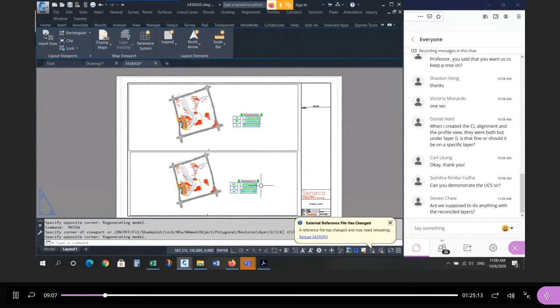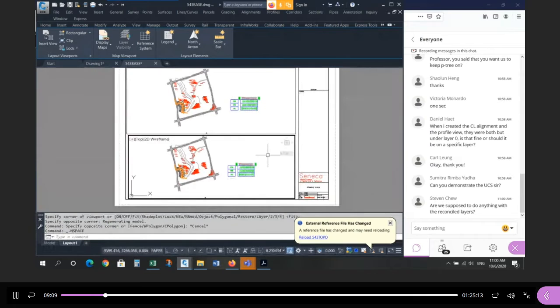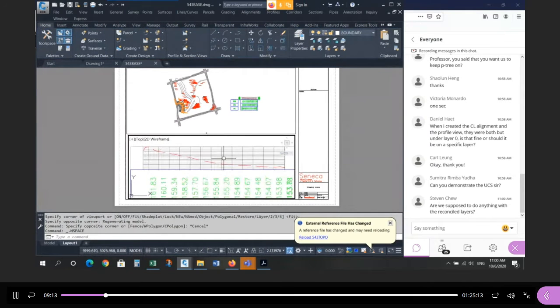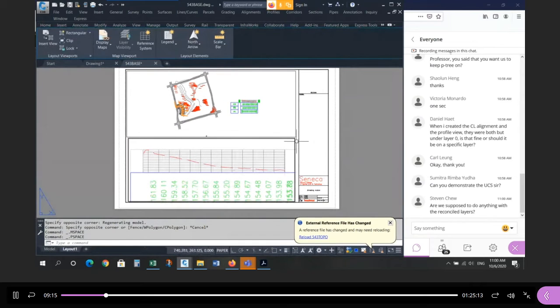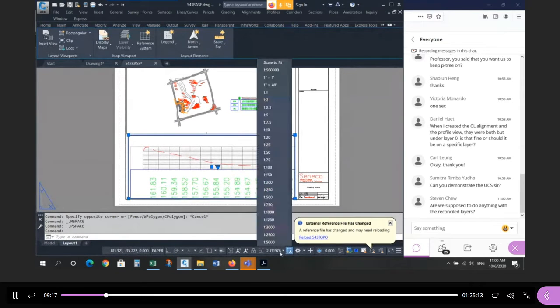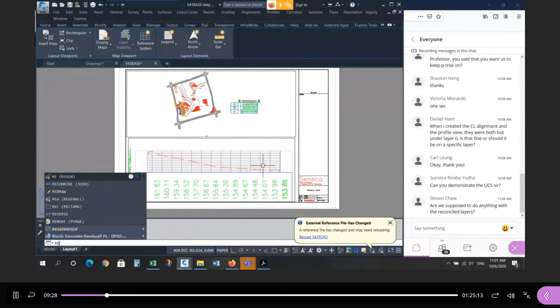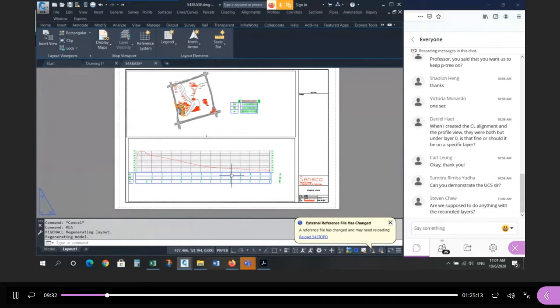So let me deal with the profile first. If you double click inside and zoom in on the profile, get it close, almost full screen, and then click out, touch the frame, and change the scale. It should be 500, which, if you list it, is 2 times paperspace. If you regen, it'll adjust the text to the right height. So regen or regen all, whichever one you use.